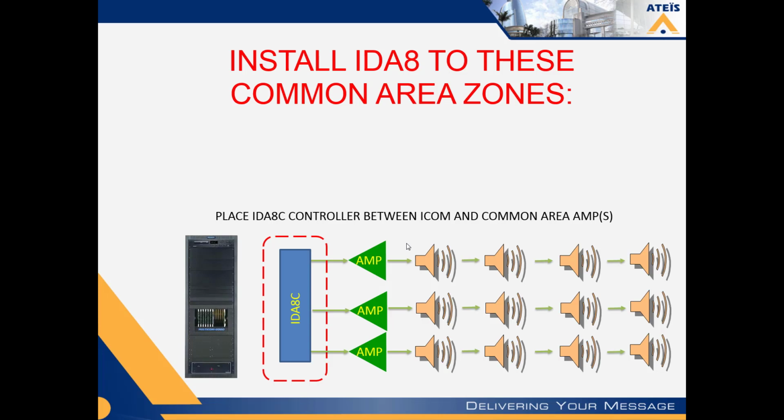A lot of intercom manufacturers out there right now are advocating replacing all the intercom systems, putting in some of the IP equipment, and then linking them together to give you some of the mass notification. But just about all of these are not listed for that use, and they run into problems with the local fire marshals or authorities having jurisdiction, or AHJ.